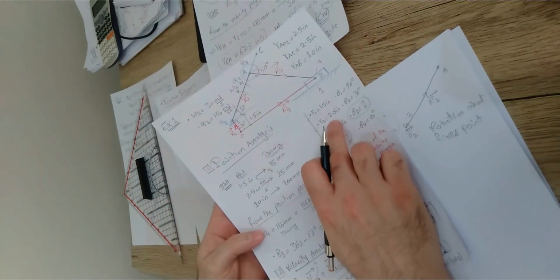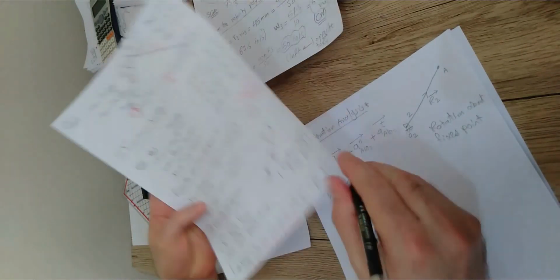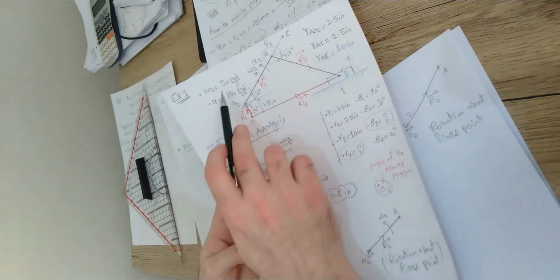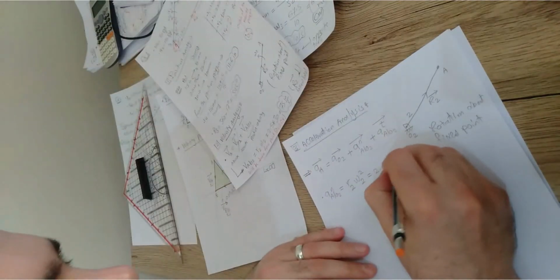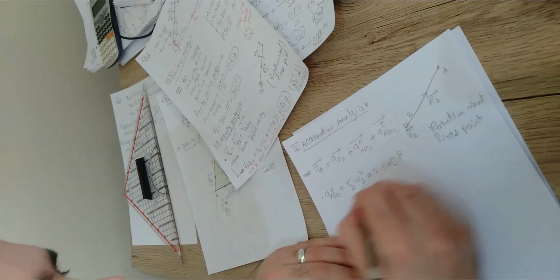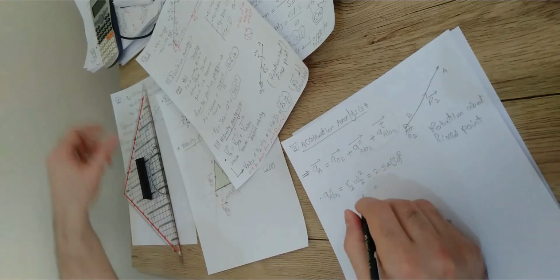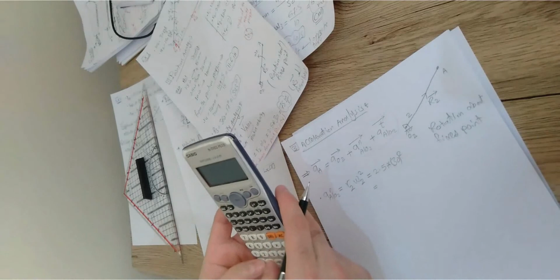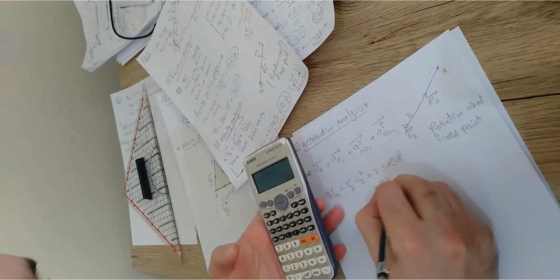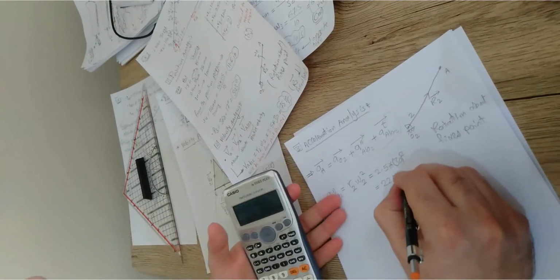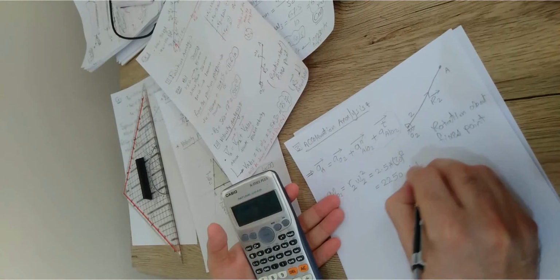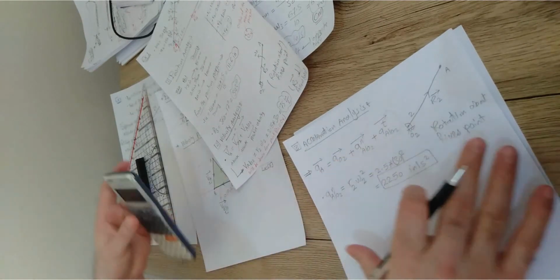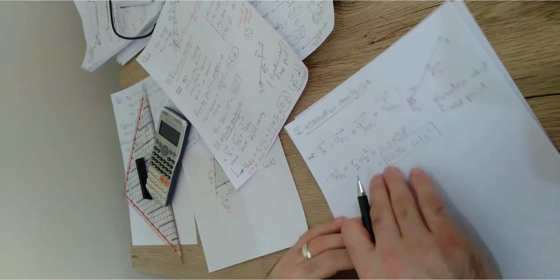We already got it from the position analysis, or it is given as 2.5 inches, so it is 2.5 inches times omega 2, which is given as 30, so 30 squared. Make sense? If we do the calculation, we end up with a value for A normal: 2.5 times 30 times 30, which gives 2,250. The unit should be inch over second squared. So this is the normal component, and it already has a value. This is for the magnitude.